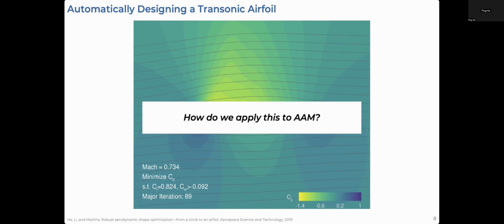Now, all of the communication starts on the OpenMDAO foundational layer and communicates with the MPhys scenarios. Each of the physical models that are plugged into MPhys communicate through the MPhys layer and with OpenMDAO. They do not communicate directly with each other. So say you wanted to use DAFoam for one optimization, but a different CFD solver for another, you could plug and play whatever components you like into and out of MPhys. And on the outside of all of this is an optimizer that controls the design variables and receives the function values and the gradients so that it can come up with a new set of design variables for the next iteration.